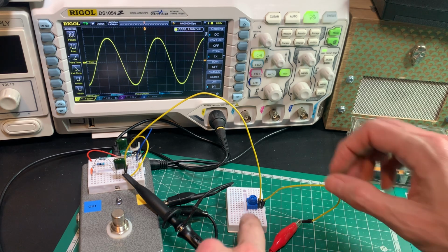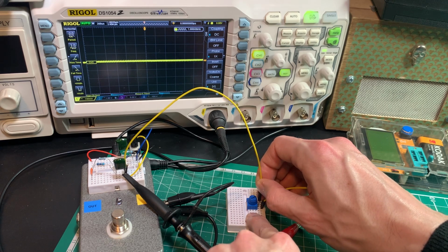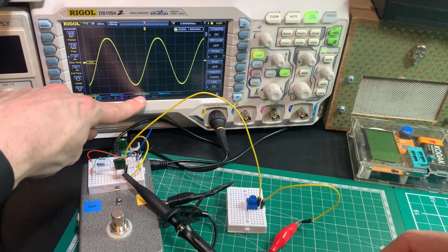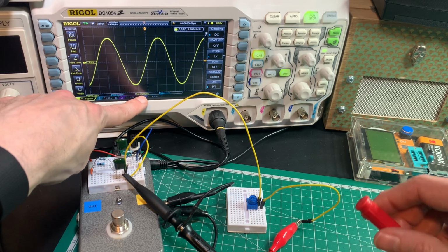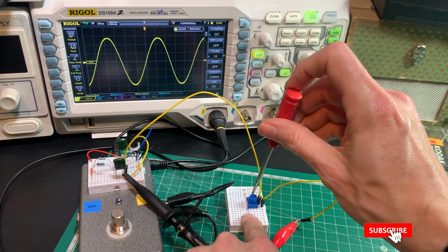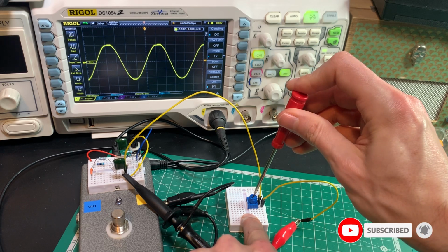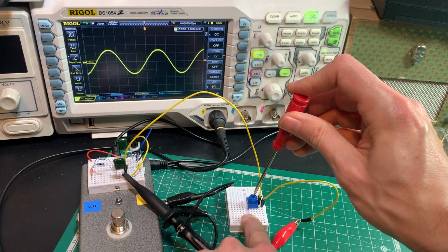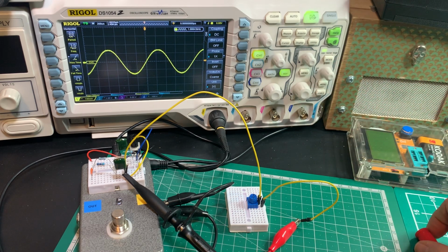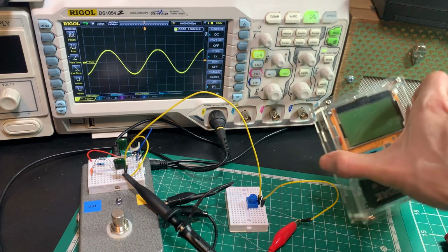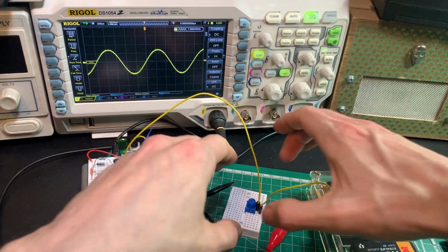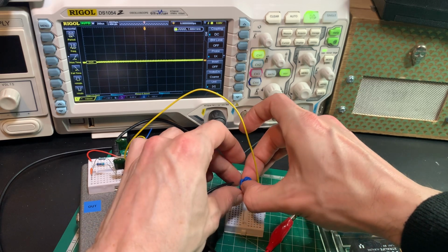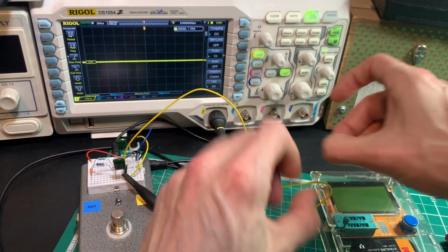So now what I'm going to do is wire in my potentiometer by moving this jumper, and we're going to reduce it until this gets down to 100 millivolts. So that's going to be around there. So now I'm going to get my component tester, and I'm going to very carefully take out the potentiometer, try not to move the setting, and move it over to here.